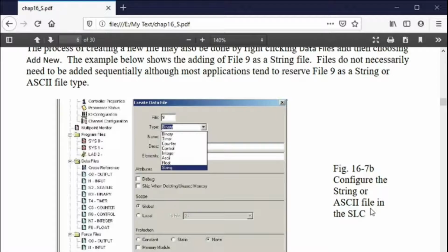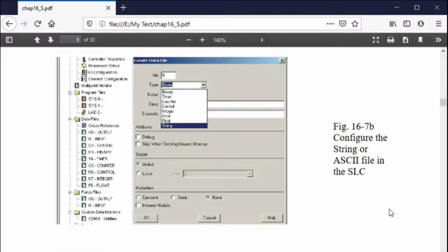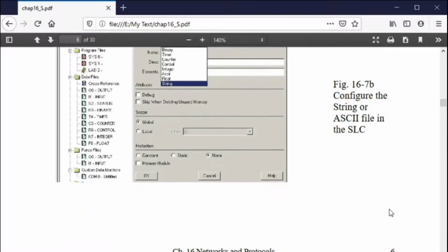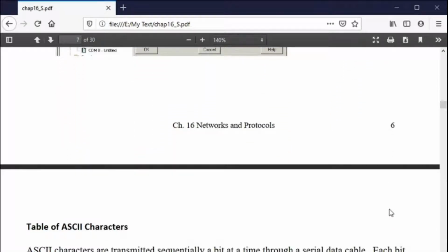Now you say, well, can Siemens do the same thing? And the answer is yes. We actually purchased with the first round of the Siemens an ASCII card that you can put on the left side of the processor, and it acted as a smart device, and you could actually do an ASCII string communication, and these are very valuable. You can even set up a specific protocol, and some of them are already given to you by Siemens. That's where some of these function blocks come in, because some of those function blocks are actually protocol blocks.